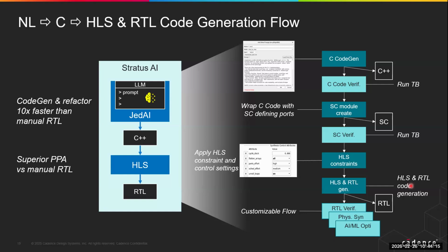Now, when you talk about high-level synthesis and this class of solutions, especially DSP circuits, then you're going to be mucking around with things like latency, right? So one implementation may have a very different kind of latency than another implementation. So your test bench has to be written such that it's insensitive to that. And usually that means there's some kind of a handshake where you say, hey, this data is ready. And then you can now go and test that data. Right? So there's a handshake before you actually start checking things. So that's kind of the flow.